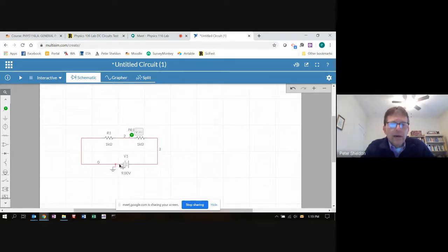So what we're doing here, and by the way, generally, not always, we'll find in electronics lab, 300 level lab, that we don't always put our ground where I did, but we generally put our ground on the negative side of the battery. And actually what a ground is, this is an important concept, is that remember that with potential energies, we always define our 0 somewhere. The ground is just defining your 0. So we're just saying, oh, here's a 0 voltage, 0 potential energy.